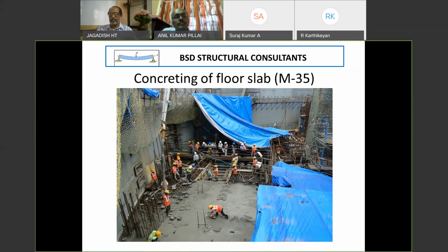Now, in addition to finish, this particular slab will have a slope. It won't be one level. There will be a number of drain pipes kept in the slab, and all the slopes are directed to those drain pipes. Why do we need a slope in a slab here? Because, as I told, there will be a number of equipment and pipelines running all over. There could be leakage, or some drops of water falling from some equipment or pipeline. Any water that is coming in the reactor building within the containment could be radioactive. If it is radioactive, we cannot leave the water to get stagnated in one place, as it starts emitting radiation. So we take the water into a drain pipe and into a tank and store it somewhere else.